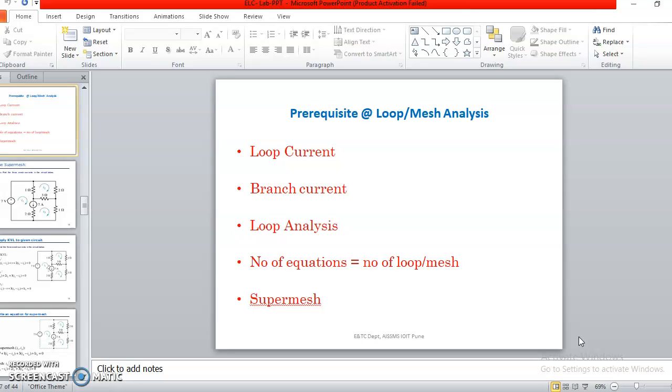The difference between Kirchhoff's law and loop analysis is that in loop analysis, instead of branch current, we consider the loop current for writing the equations. In this method, if any branch carries more than one current, then the total current must be decided by the algebraic sum of all currents through that branch, which we have discussed just before.